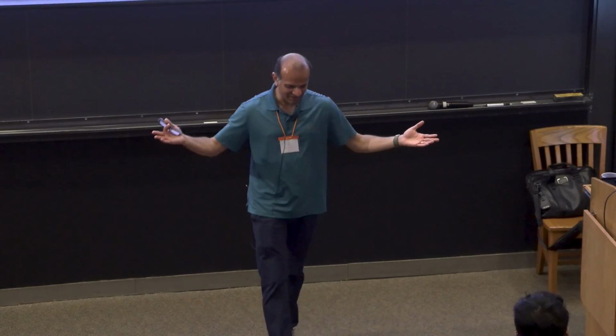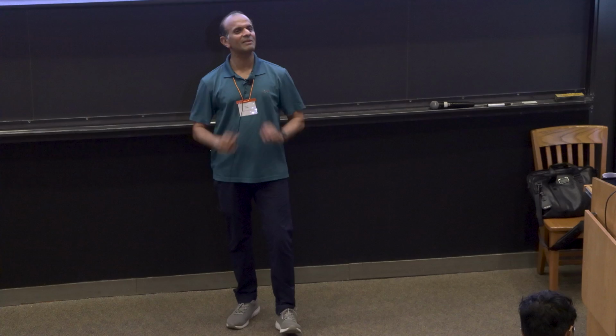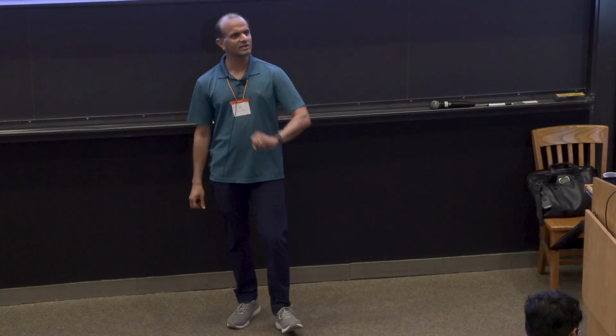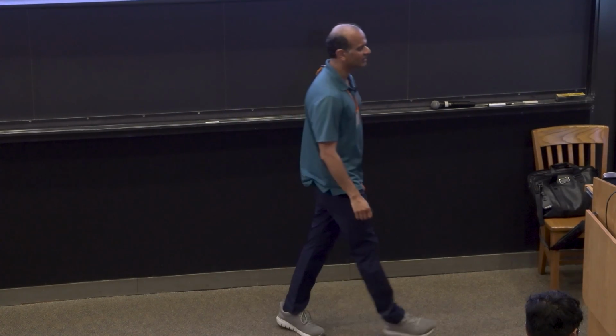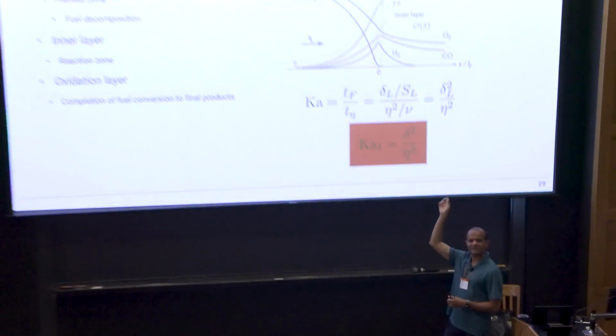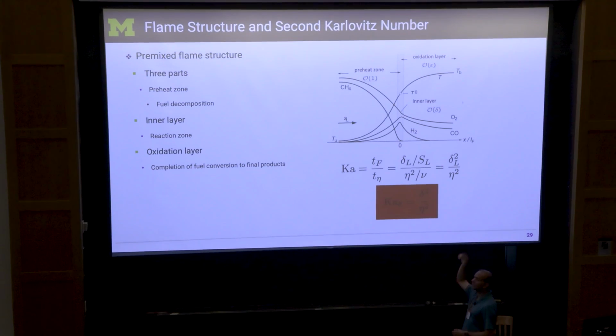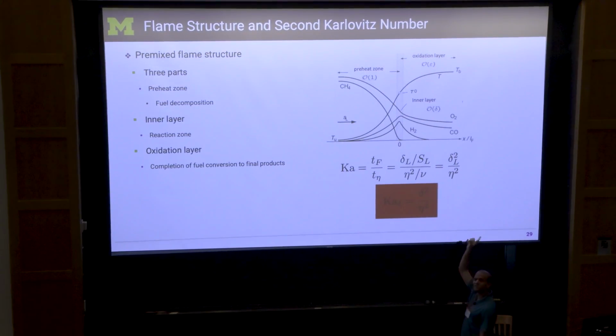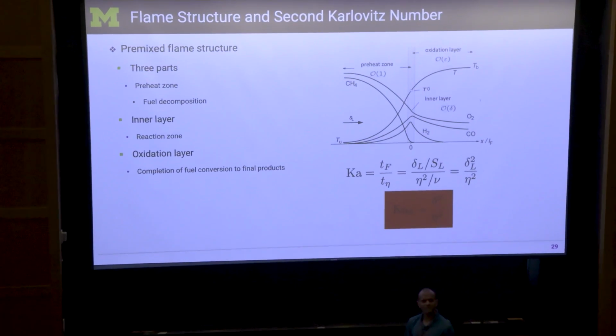So if you take a laminar flame, and you probe into what's happening inside that flame, okay? Of course, using computations, you can do this using experiments also. You'll find this characteristic plot. So the x-axis here is just the x-axis going across the flame, okay? So the flame is located around 0. So that's where everything is happening.